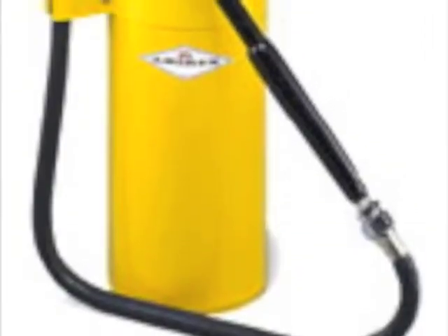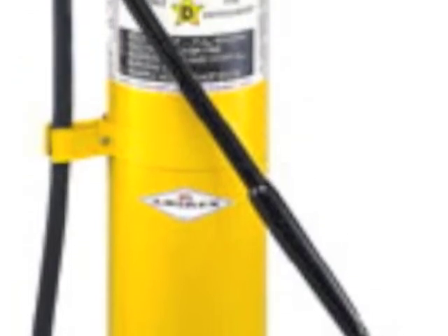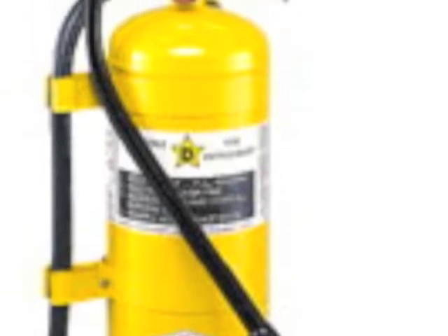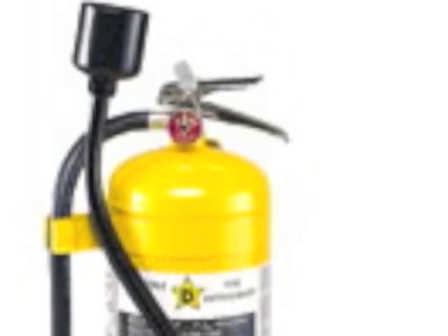Dry powder extinguishers are similar to dry chemical, except they extinguish the fire by separating the fuel from the oxygen element or by removing the heat element of the fire triangle. However, dry powder extinguishers are for Class D fires only. They are ineffective on all other classes of fire.